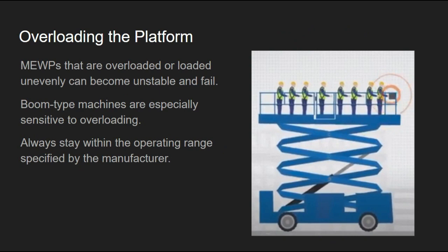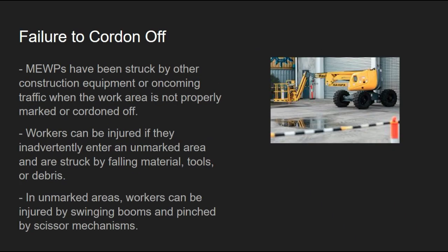Overloading the platform. MEWPs that are overloaded or loaded unevenly can become unstable and fail. Boom-type machines are especially sensitive to overloading. Always stay within the operating range specified by the manufacturer.